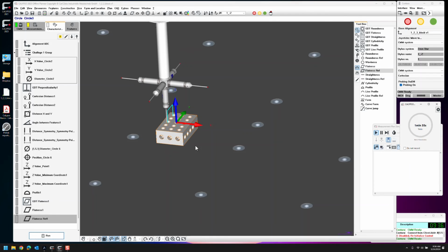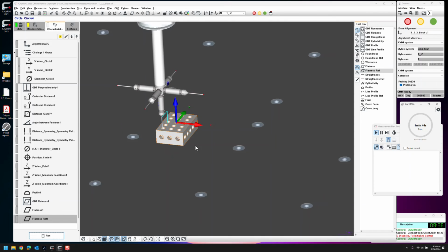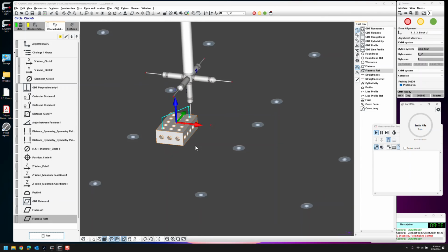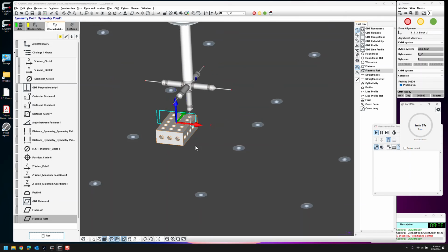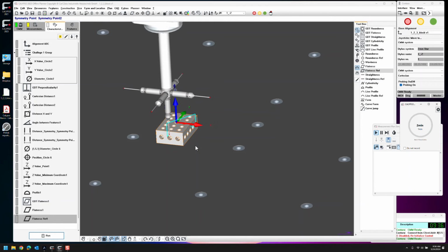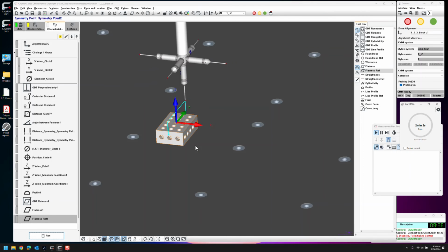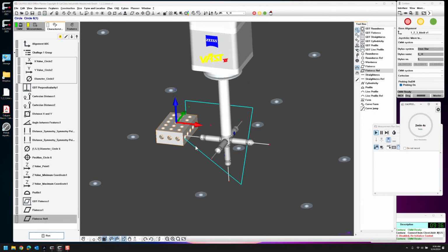So go slow, see what the slow conservative speed result is, then start doubling or 50% increases in speed until you start to see the form and standard deviation change by 1/10 of your tolerance. At which point, also look at the result. Like if it's a diameter, you want to see if the diameter changes. If it's a location, you want to see if the location changes. By whatever you're measuring, changes by 1/10 of the tolerance, plus standard deviation, plus form. And if you get all of that right, then we would be maximizing our speed.